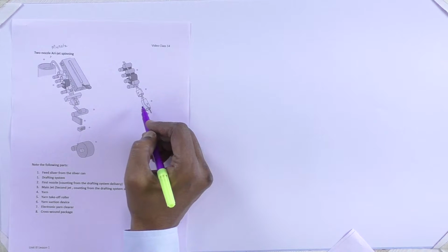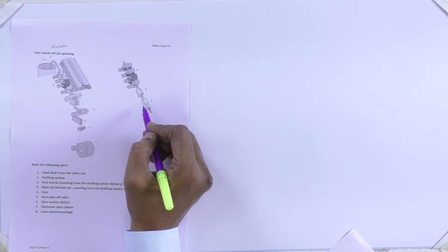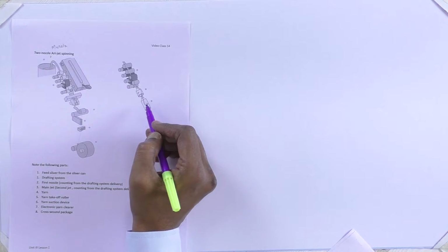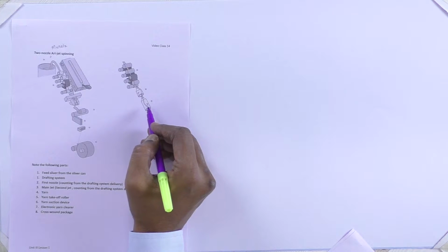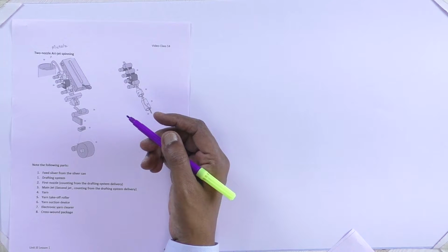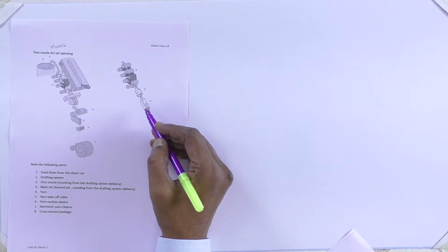Air vortex with a speed of 2 million RPM, that is, in other words, 20 lakh in Indian terminology. Compare this with ring spinning, 20,000 RPM, and 200,000 RPM in rotor spinning. The air vortex rotating with a speed of 2 million RPM is generated in the second nozzle. The strand gets twisted due to the air vortex.